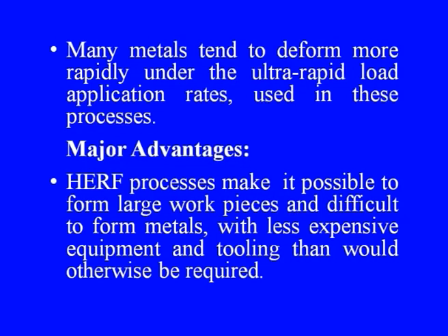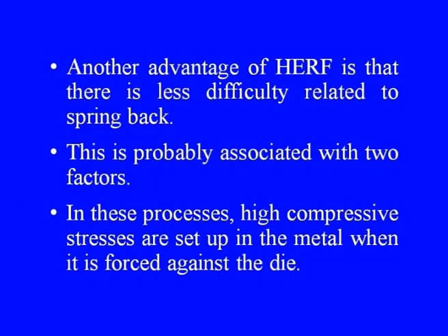Thus, if we see the major advantages of this process, high energy rate forming processes make it possible to form large workpieces and difficult to form metals with less expensive equipment and tooling than would otherwise be required. Another advantage of high energy rate forming process is that there is less difficulty related to spring back.